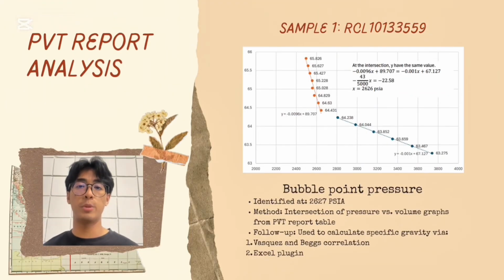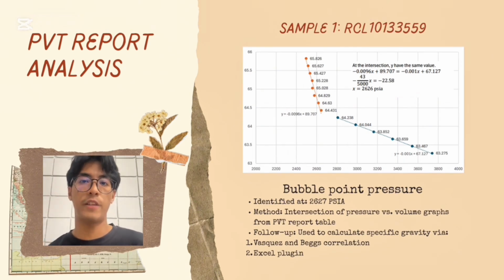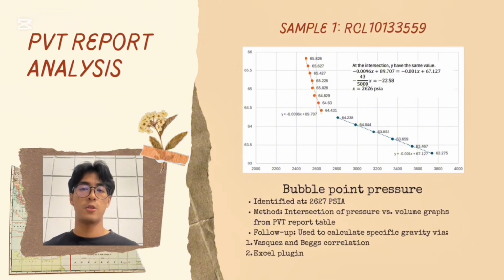Alright, so now I will be doing a full analysis on the first sample, which is sample RCL 101-33559. So the first step will be to determine its bubble point pressure. From the PVT report analysis, there is a table with various pressures from 2000 to 3000 plus with their different volumes. From the values in the table, we can make 2 different graphs of pressure against volume, and find the intersection between those 2 graphs, where the intersection would be the value of bubble point pressure, which in this case for sample 1 is